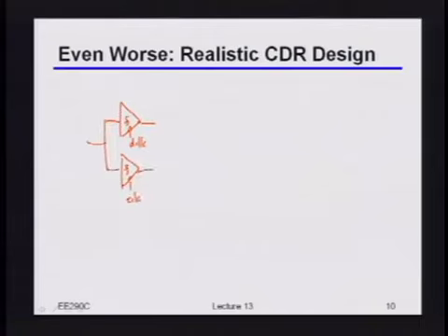Then I will shove this into something that looks like a big bank of flip-flops, where there are two clocks. One is equivalently the data clock, as an example, 12 gigahertz if you're doing a 12 gigabit per second link. The other would be something like the data clock divided by 10, or maybe divided by 12, or even divided by 24.